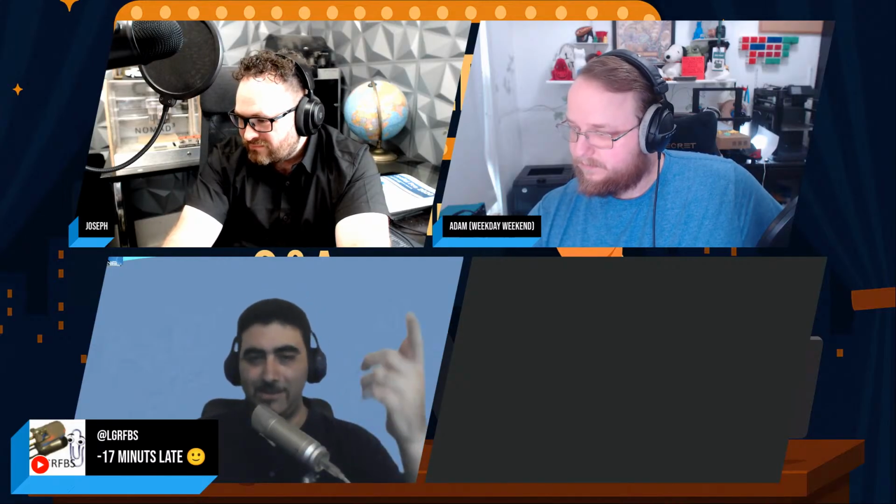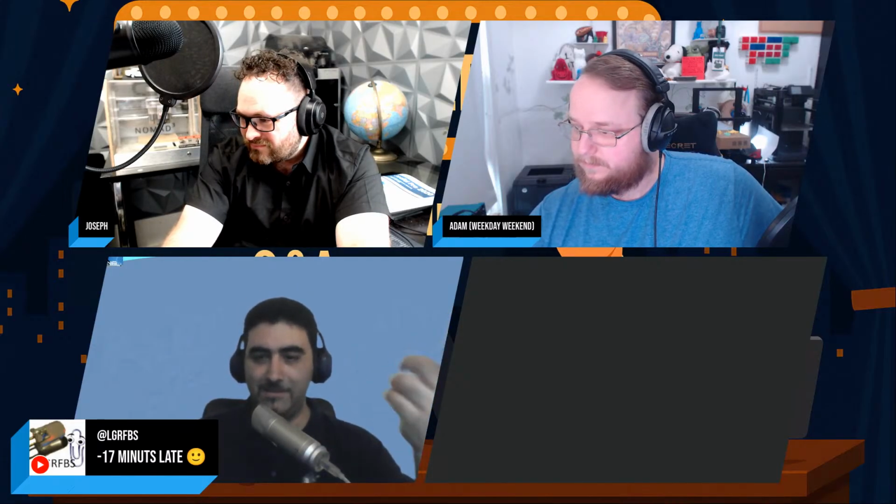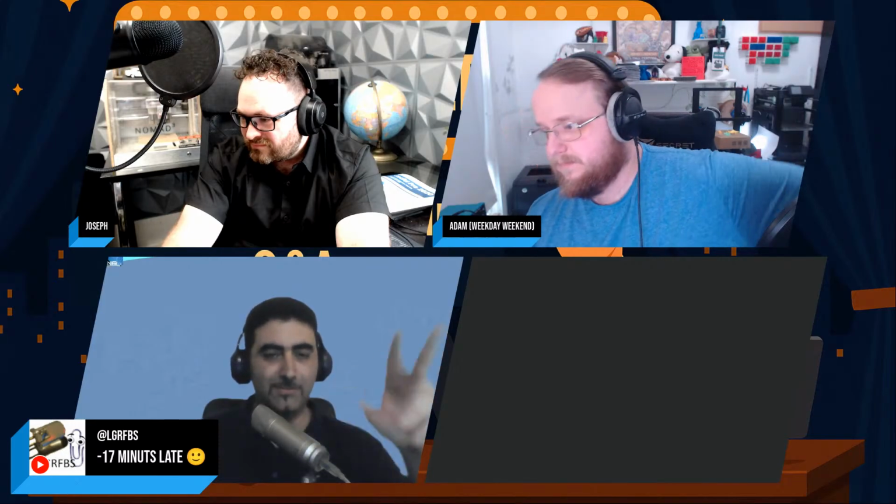Whereas the TPI one is easier for the engineer to calculate if the fastener can take the load, the preload you want to apply. Because for the preload, you need to calculate how many threads are in engagement, right? And the effective diameter of your bolt. So inch is easier to calculate loads. Metric is easier to manufacture. There's an interesting tidbit for you. Interesting. Yeah, that makes a lot of sense.